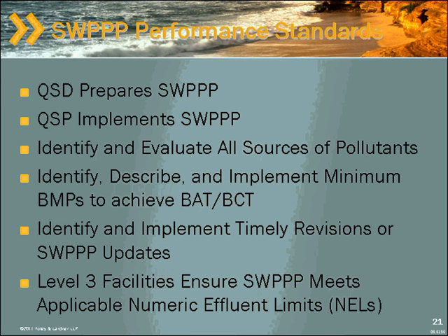Again, I'm making up this hypothetical, but I blow through suspended solids. Okay, I file a corrective action report. I say, well, gee, I used to sweep once a week. Now I'm going to sweep twice a week. Is that sufficient to be able to say I've met BAT-BCT? Or is there a challenge that says, wait a minute, we really think you should be sweeping once a day? How are we going to deal with that? That's a very real issue, Wayne.